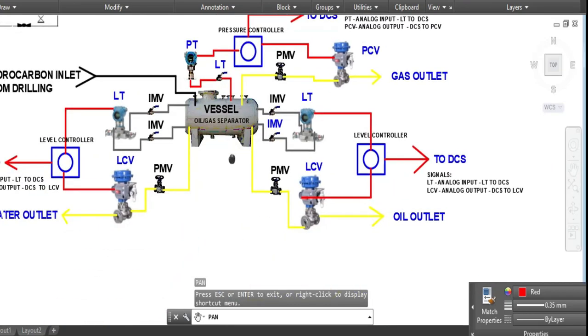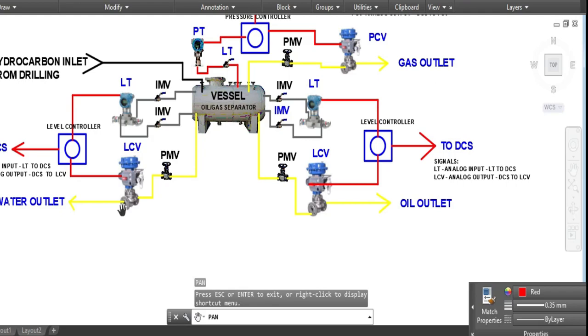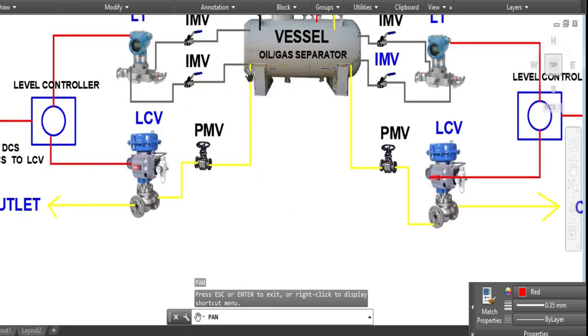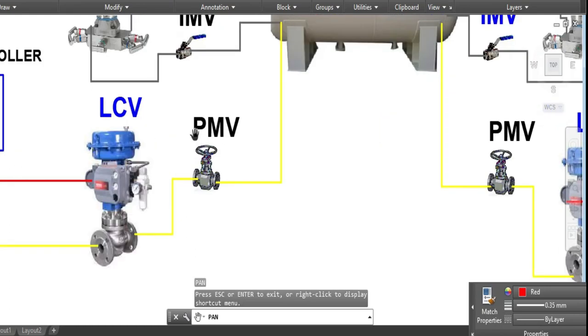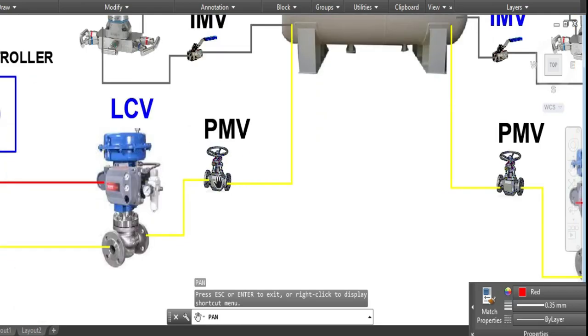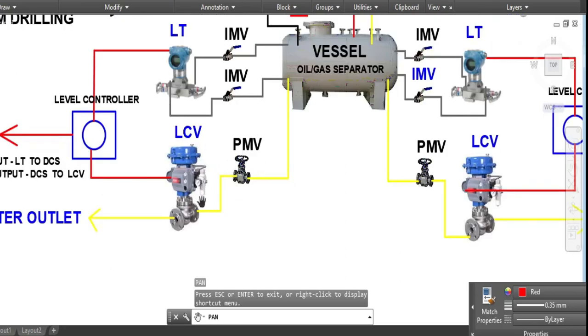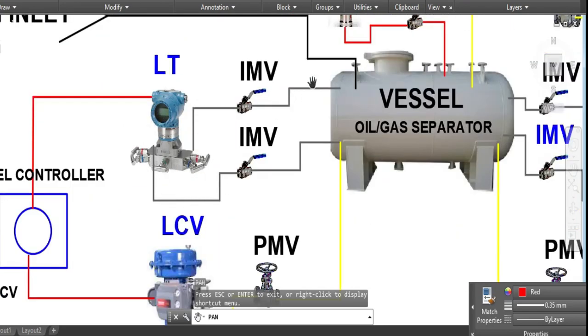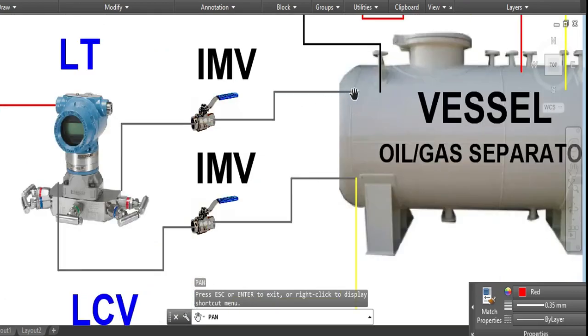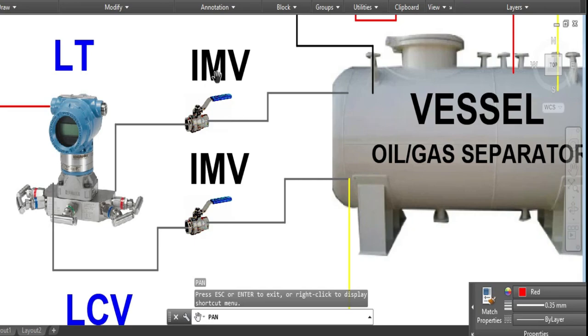And then now I'm talking about the piping connection of the valve. From this side, this is piping, which comes to the PMV, or piping manual valve, so that anytime for maintenance, we can isolate the process lines by this PMV if we have maintenance of this control valve. Also this level transmitter: normally the connection from the vessel should be stainless tube. This should be stainless tube, and also this one, the IMV, or instrument manual valve.